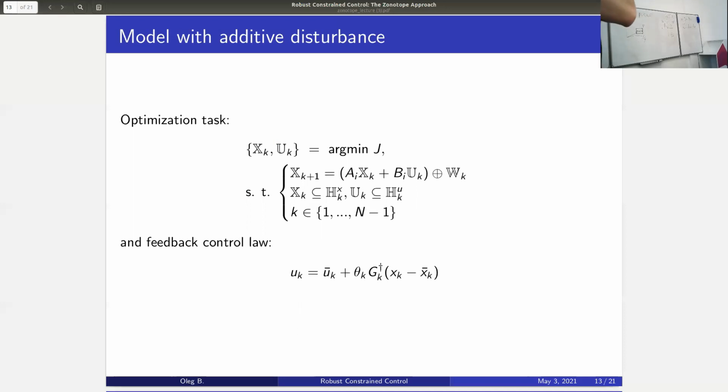Just a bit technical question, because when you do this optimization, certainly something is not feasible for your system, right? Some motion is not feasible, and your solver will say, okay, it's not feasible. So then it becomes a play with the sizes of Zonotopes and different stuff to make this happen, so that finally you may reach this. If your algorithm does this for you, it's much more convenient, right? So you can say, okay, you may reach this size of Zonotope, you may reach this size, you may reach this tube.